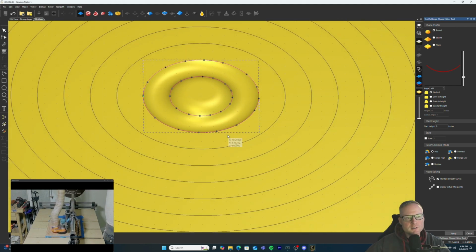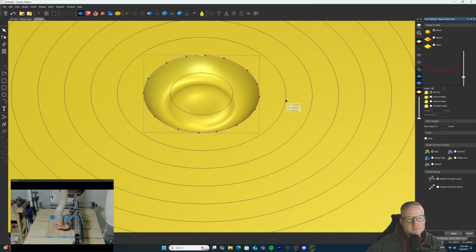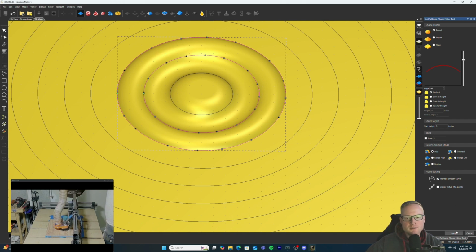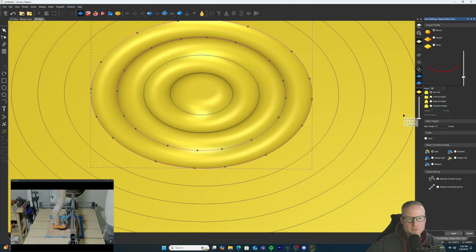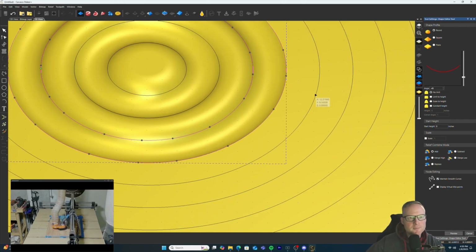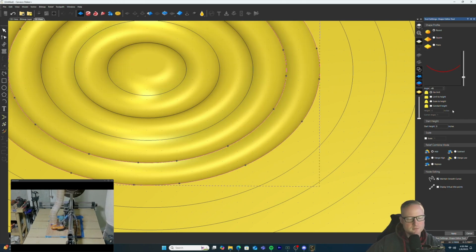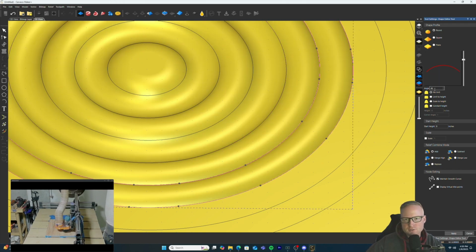And all I'm going to do is alternate between these vectors and get the shape in like an actual ripple. So I'll go ahead and select my next two vectors. And this is going to be a +45 on Apply. Next two vectors will be a -45. Apply. One will be a +45. Apply. And so on and so forth.